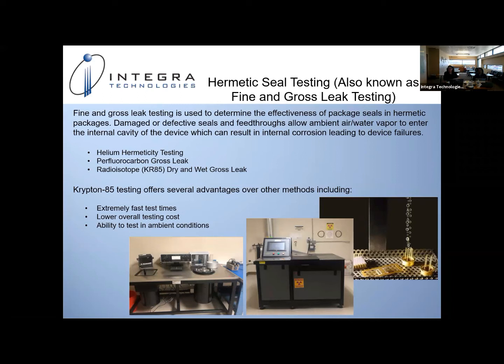All right, seal test. Did I answer all the questions for XRF? Perfect. All right, so hermetic seal testing, also known as fine and gross leak testing, is commonly performed with hermetic type packages. Again, it's just hermetic packages that go through seal testing because they have the cavity.